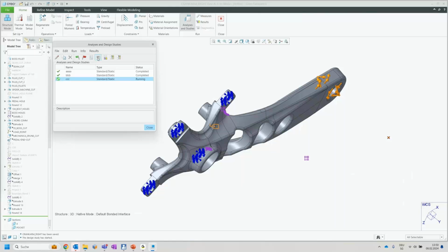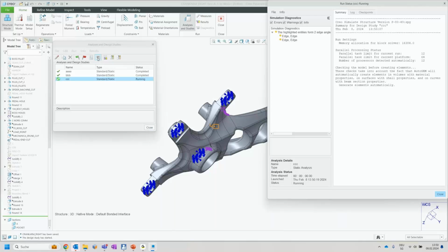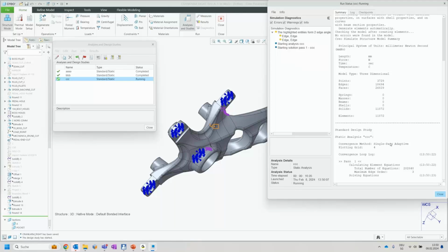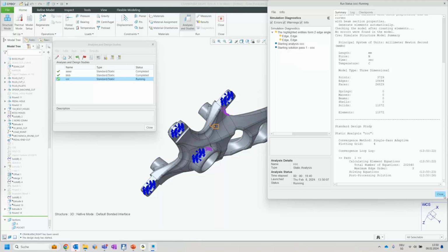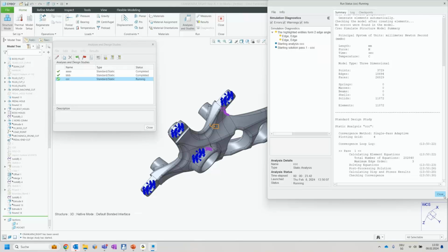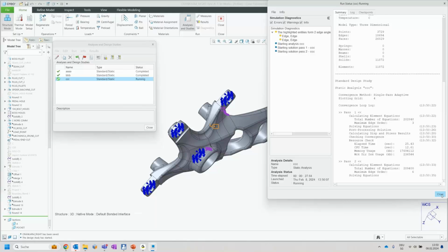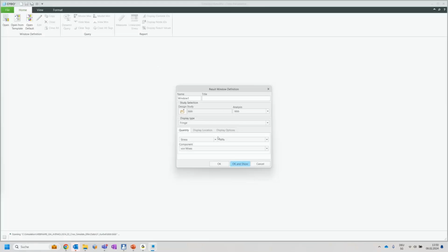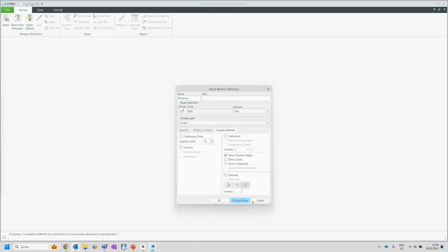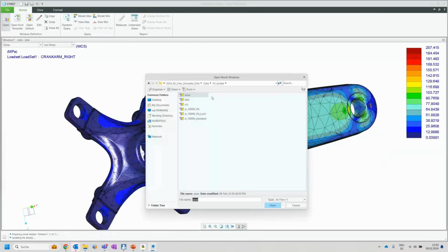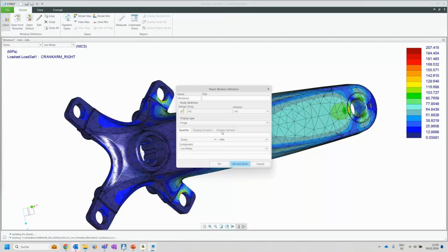I can check that here in the status file. Okay, meshing is done. Again, around 12,000 elements, and that takes me 20 seconds, something like that. And now I really can compare the first version with the second version. Is it possible? What are the stresses doing? I'm going for the first version here. In the post-processor, I want to see the stress behavior with the element edges. Looks like that. And in addition, from the version CCC, I want to see the same things.